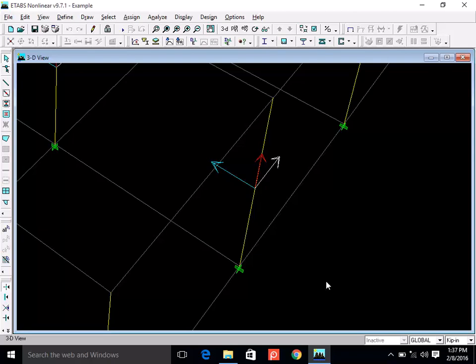Okay. There may be a situation where on this side of the beam you have different loading. Maybe there is a store and it is heavily loaded, and on this side you may have an office. Load is less. So although the dimensions are symmetrical, the magnitude of loading is unsymmetrical, then you will have bending moment about this axis as well, right? Oh, sorry, this axis, this bending moment.